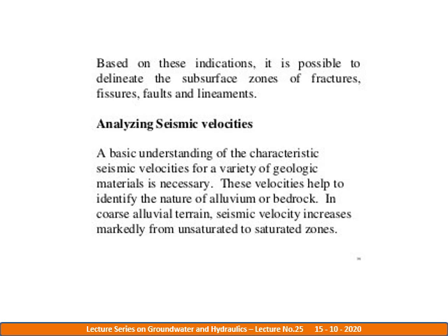For analyzing seismic velocity, a basic understanding of the characteristic seismic velocity for a variety of geological materials is necessary. This velocity helps to identify the nature of alluvium or bedrock in coarse alluvial terrain. Seismic velocity increases markedly from unsaturated to saturated zones.